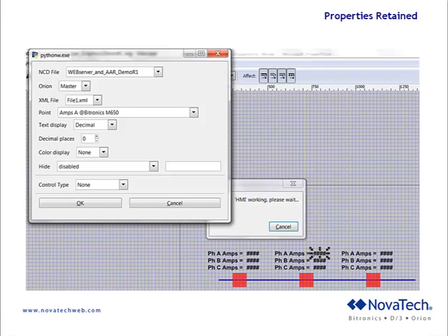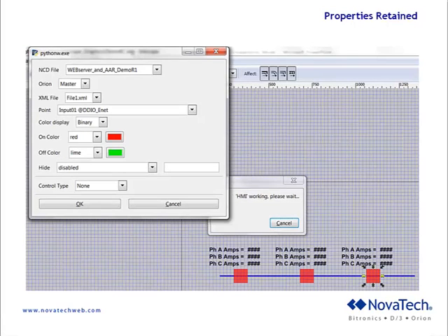That's where all of these point names will be an indirect address, and will populate a value that brings in as you select the page. And we'll talk about that in just a little bit. And if we click on the breaker in the third position there, you'll see that the properties and parameters have been retained for that as well.